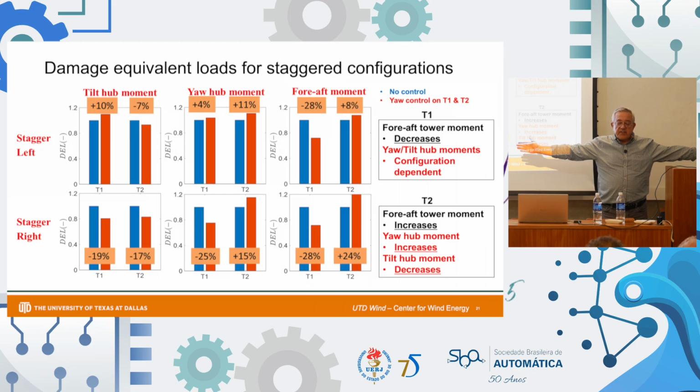The first turbine was facing the wind. It's going to have the highest wind hitting me, so the fore aft motion is going to be more impacted. If I rotate a little bit, now I see a smaller wind speed magnitude, and I'm going to move less on the tower.